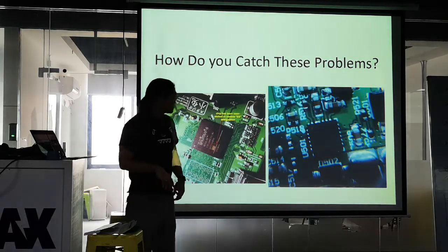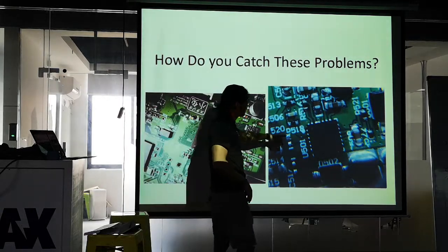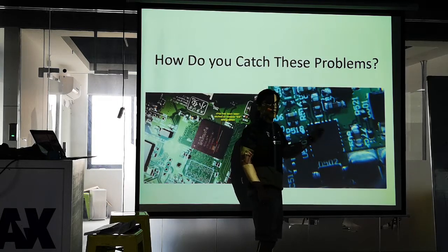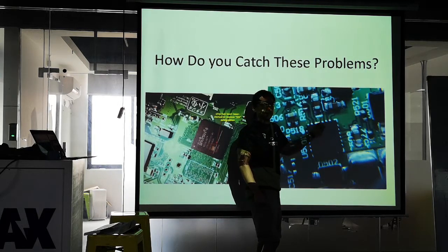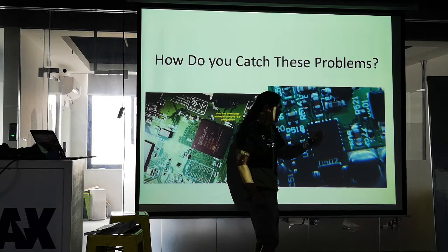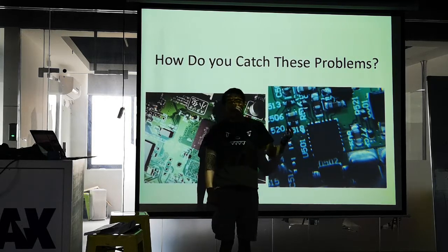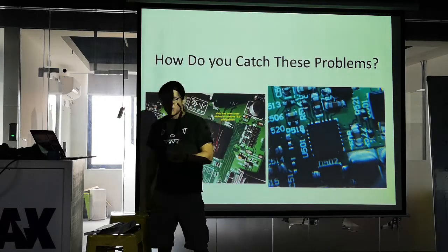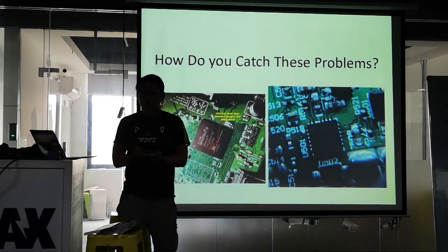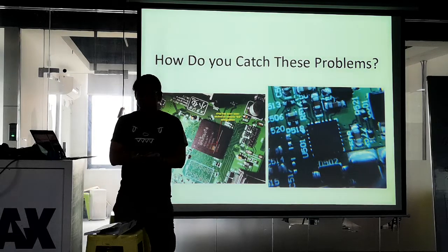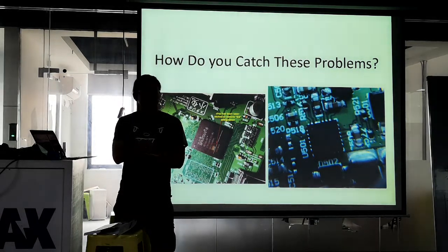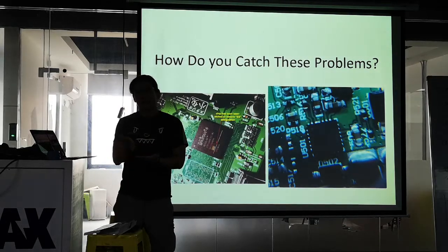Another problem, for example, is this is a QFN, right? This is actually a really common issue where you have a small short circuit between two pins on the QFN. QFNs are actually, in my opinion, more difficult than BGA for yield, because the QFN has the metal pad on the bottom side with the solder. When the solder gets up to temperature, the flux will volatilize and gas will come out, right?